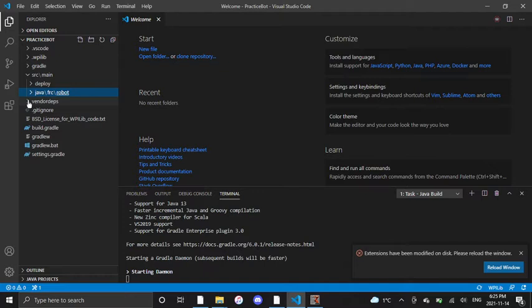To install our extension, you're going to open up this vendor deps folder over here. This is going to be vendor dependencies. We have these dependencies because of all of the different motor controllers, the speed controllers we're getting from CTRE, or Cross the Road Electronics. Over here, you'll see that there's a vendor deps folder as well. Perfect. So we're going to open up the vendor deps folder, and you'll see this Phoenix JSON file, phoenix.json, and I'm going to drag that into this vendor deps folder over here. So you should copy into it.